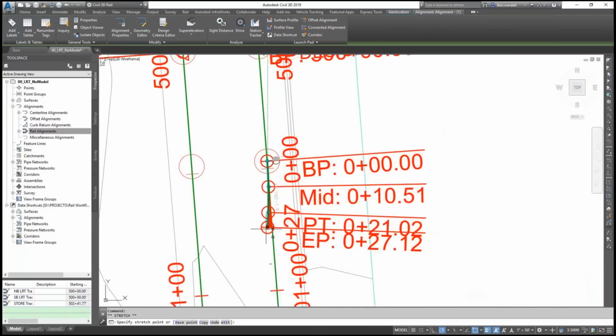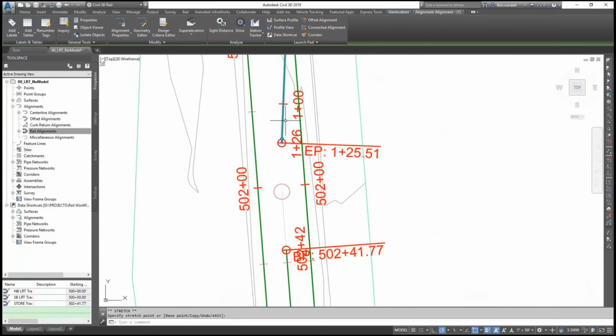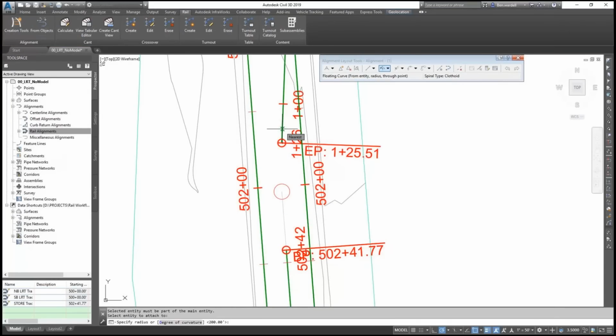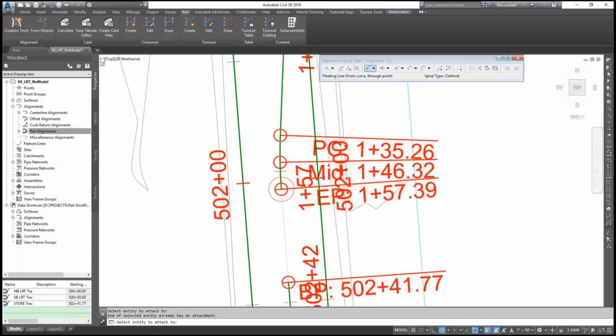There are some in between, but it is pretty powerful if it fits for what you need. And so there are some limitations to it. That is in the works to become completely available for all the turnouts. But in this case, once we set that turnout, all this geometry is stored, and we can add to this just as we would in normal alignment. We can add the tangent here to connect to this center track.